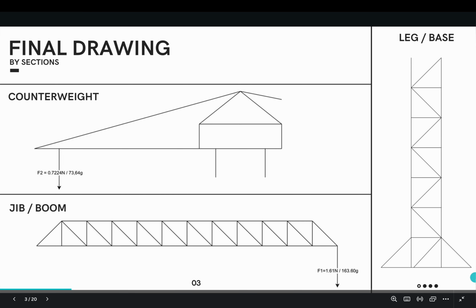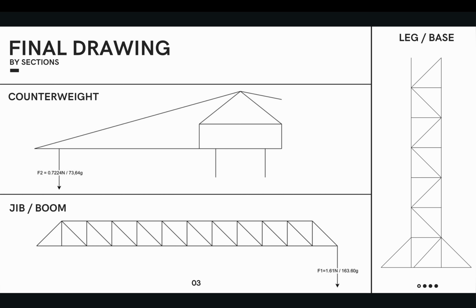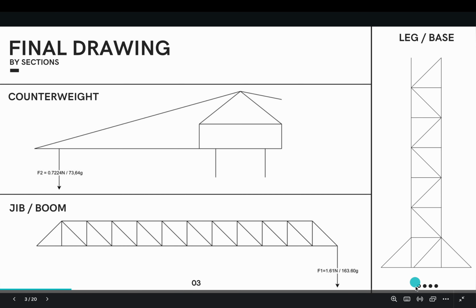To find the applied force at the base, we assume that all these four are equal. So we use sum of y equals 0, which is negative F2 and negative F1 equals 4N. We assume that the applied force is labeled as N. Then we use method of joints again to find the truss until this part.